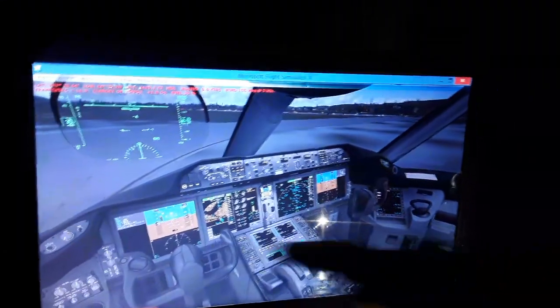We have 30% also in the center tank, and the loads from the compartments and the passengers are going to give us the center of gravity position. It's going to be 23% of the mean aerodynamic chord. The position of the maximum aerodynamic lift occurs in the forward wings, so the position where the stall will begin for a given angle of attack in flight. The airflow will become detached from the top surface of the wings, and pay attention over here.